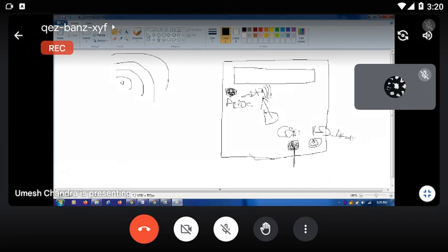One terminal is connected to the common position, then the other terminal of the black lead is connected with the red lead. Just connect both. Now short circuit. If the two leads are correct, then one sound is coming. That means the two leads are working properly. If sound is not coming, it is not working properly.